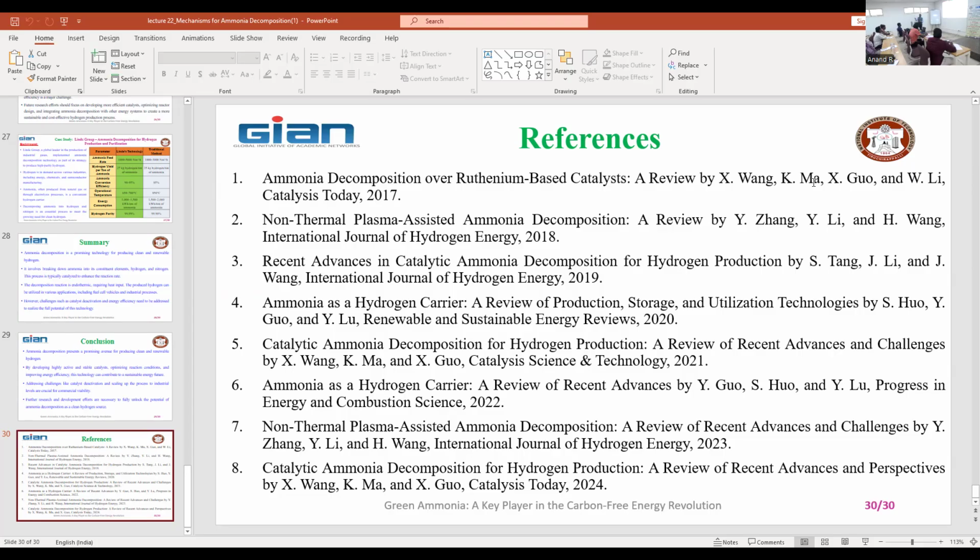We tried with biodiesel actually. We ran it for the same number of hours as with diesel, and we showed that for biodiesel there is no need for any replacement of the material. But some components need to be coated against corrosion, particularly the rubber as well as the copper components.